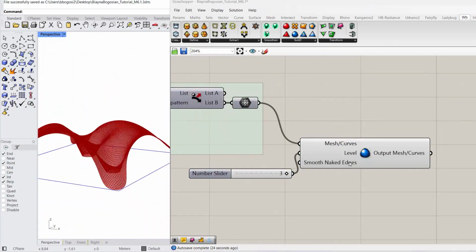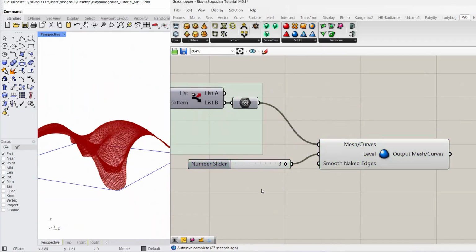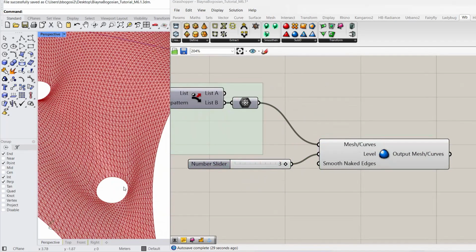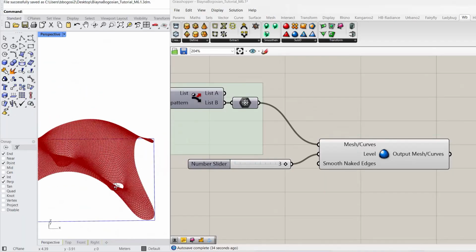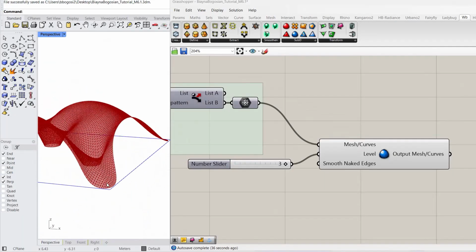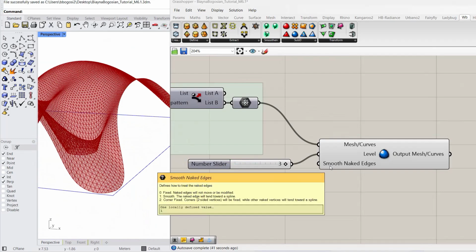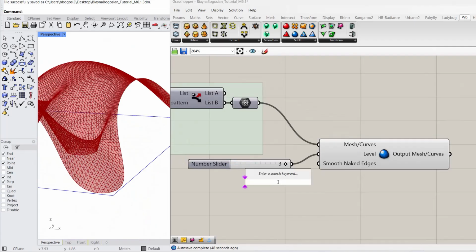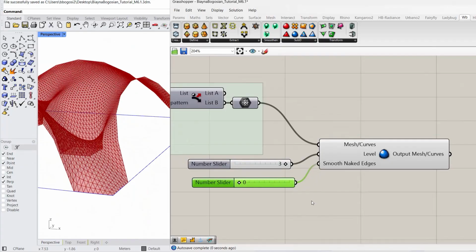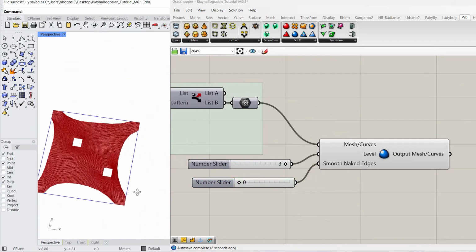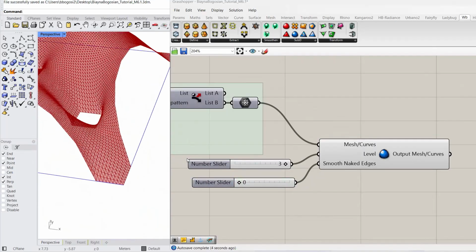surface to look at. Then there's other features as well. So for instance, here, it took basically those corners, and right now it's completely rounding this. Now, if I like this effect, I can definitely keep it. But if I do want to keep the anchors as is, I can change these variables here. So 0 is fixed, 1 is smooth, 2 is only connect the corners. So let's make a slider that goes 0 less than 2. And if I connect this with 0, you can see that it is actually keeping the corners, which actually I think that works really well.